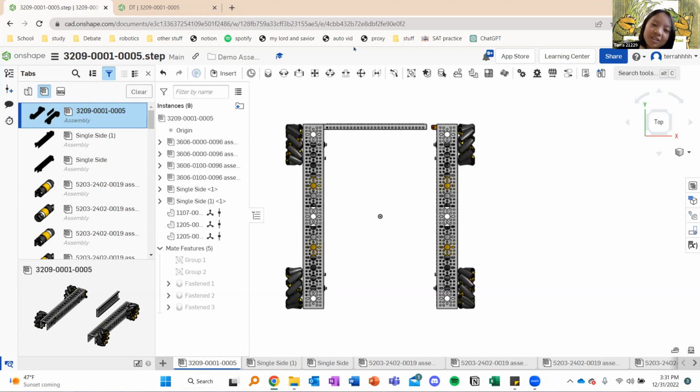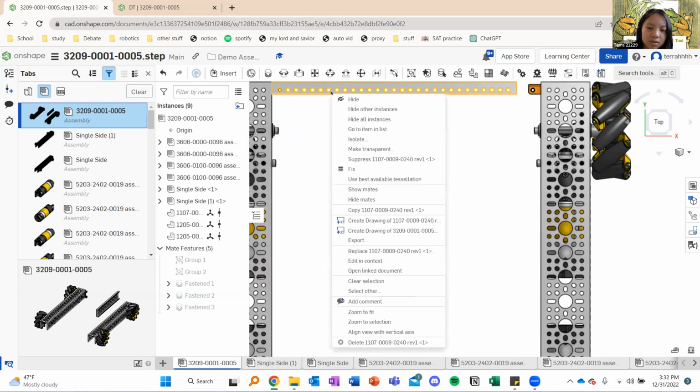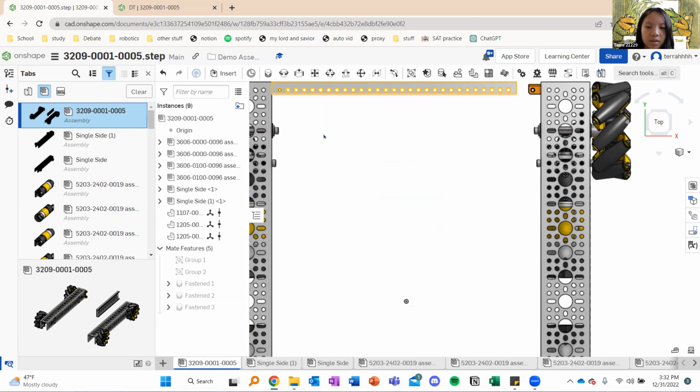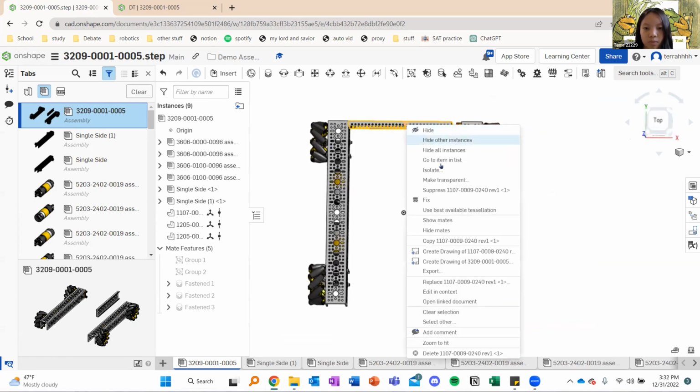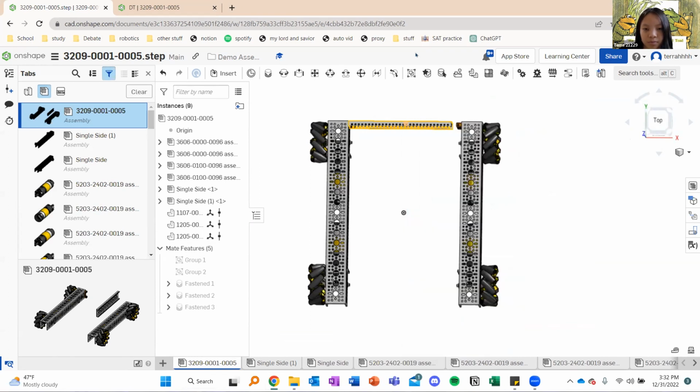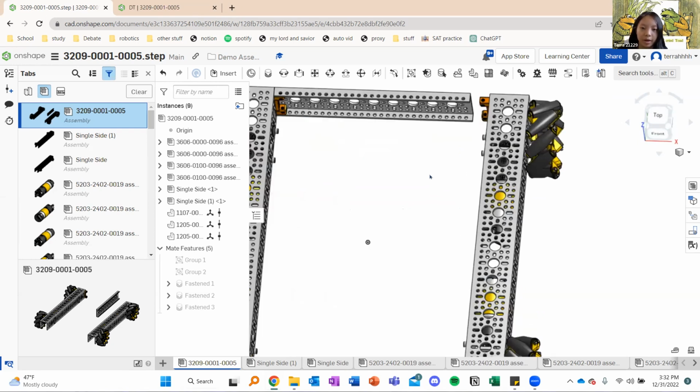I don't think the part color really matters. I'm actually not sure if you can change the color. Does anyone know if you can? I think it's just with step files. You can assign materials to particular parts. In assembly, on the left side, you can right click, assign a material, and you can create materials and assign color. But that's not the main content we are going to talk about today. It's mostly for rendering, more of a decoration purpose. Yeah. Okay. I'm going to move on now.